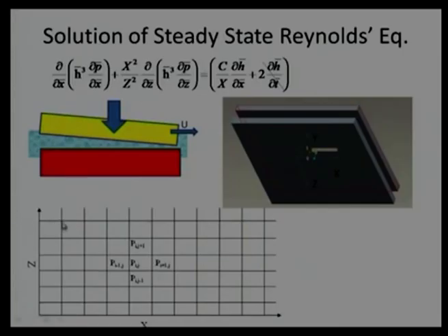That is why in the z direction and x direction, these lines are parallel lines and perpendicular lines. They are going to give us some nodes, and we are interested in finding the pressure at some nodes. Assume this is the I j junction, and we are taking help of neighbor nodes. Neighbor nodes are going to help find the solution, and it is an iterative procedure. I am going to explain how it is an iterative procedure and how these neighbor nodes are going to help us.